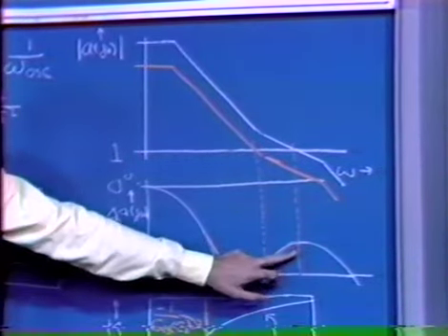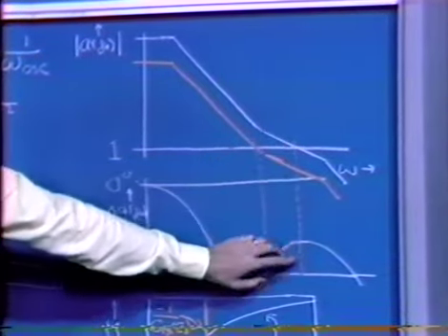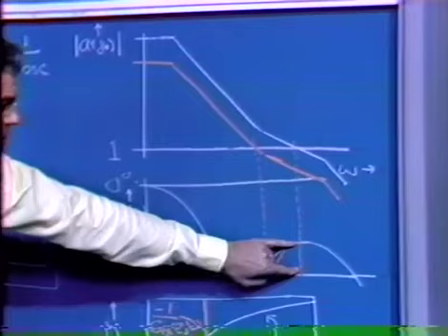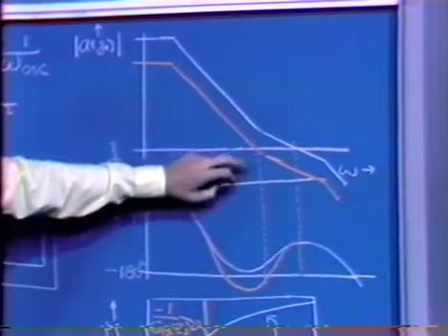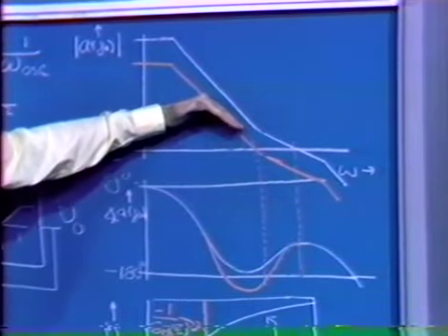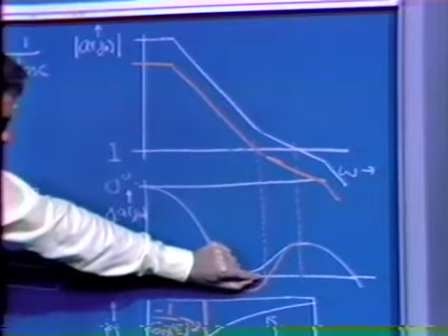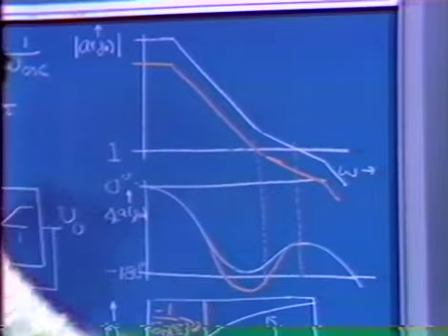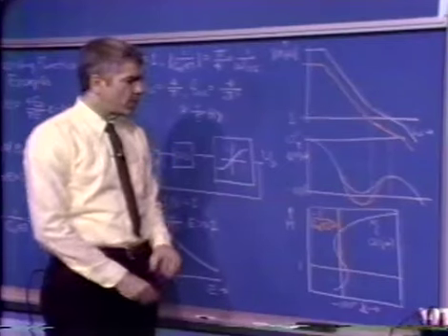Now again, we could hope to have the characteristics arranged so that there was perfectly adequate phase margin at crossover in the absence of saturation. But if the system's saturated and the curve in a describing function sense moved down because of lowered gain, as I've shown things, we'd actually cross over in a region of negative phase margin. And that sounds as though there's certainly the potential for very bad performance in that situation.